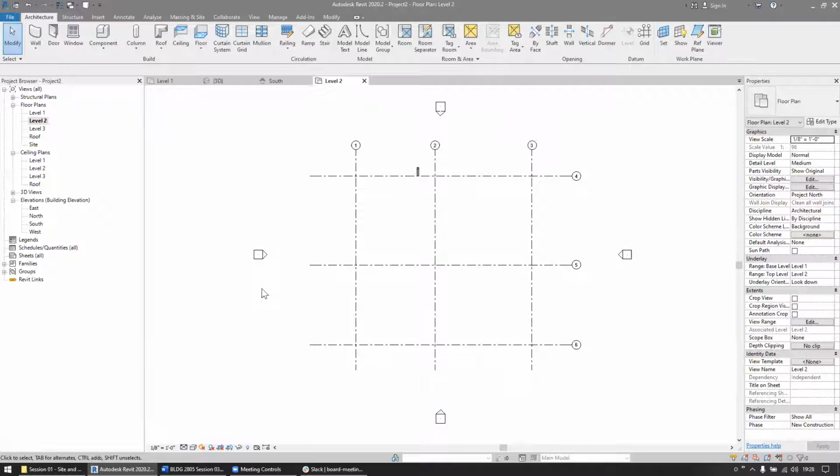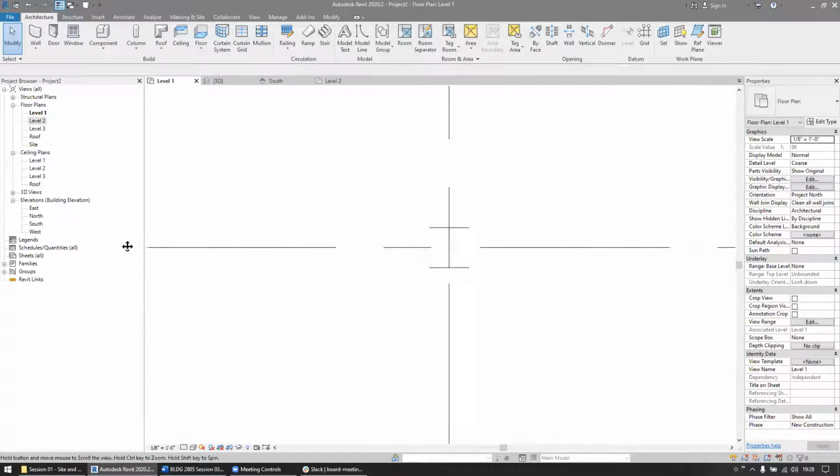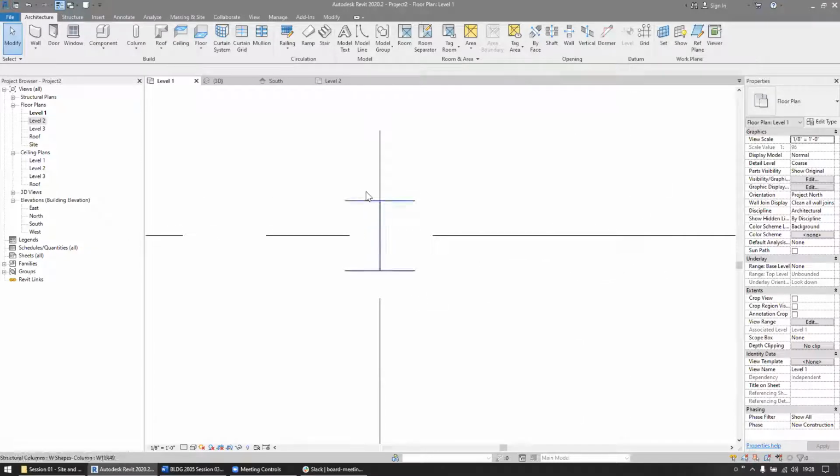Now, there's something to keep in mind here. Level of detail becomes more important with structural engineering objects. If I turn on thin lines mode here, when we're looking at a column, it looks like the columns don't actually have any thickness. But once we get into medium mode, you folks can see, hey, now we've got the actual physical thickness of these flanges.